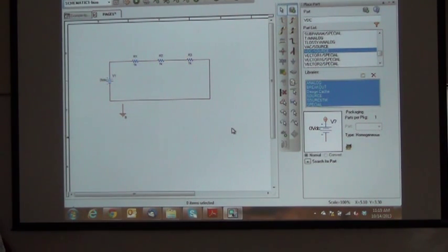Oops. Now I'm going to go ahead and connect my ground symbol. Now I can click my select tool, and when I click on the screen, notice that it puts a little dot there, a connection point. So now we have a complete schematic.